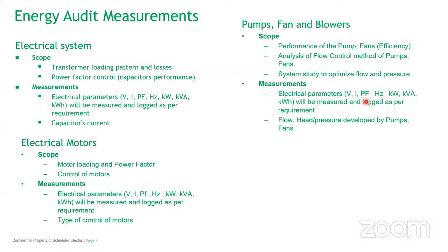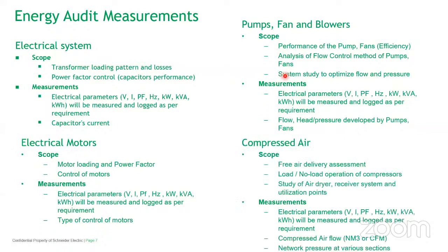Again, we should know the electrical power consumption, and then we should know the hydraulic power based on the flow and head pressure. We should know the hydraulic power which has been fed to the pumps and other areas. By dividing hydraulic power by electrical power, we'll know the efficiency of the particular pumps and blowers.